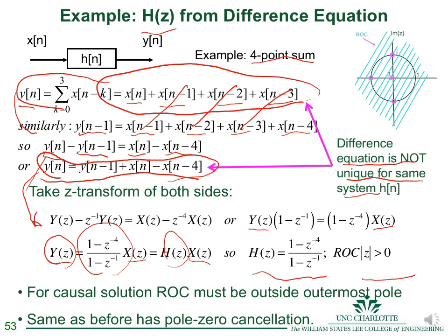And so it has a pole zero cancellation. So it has a triple pole at z equals 0, and it has 3 zeros at z equals j, z equals minus j, and z equals minus 1. The DC response is a little difficult to see in this form because I have 1 minus z to the minus 1, so 1 minus 1 in the denominator if I evaluate this DC response.